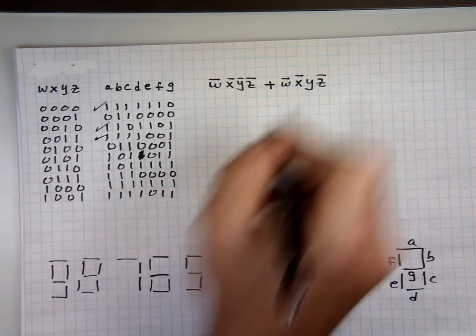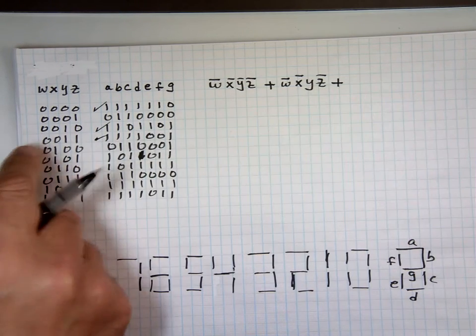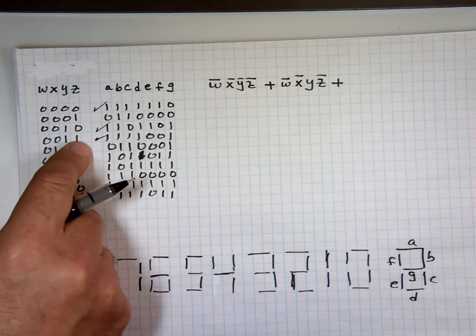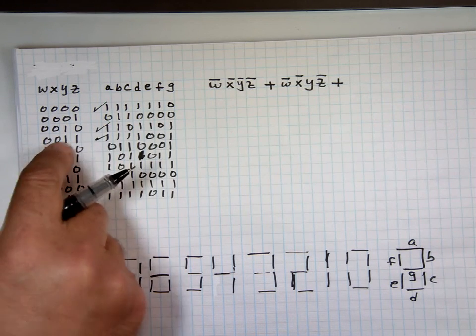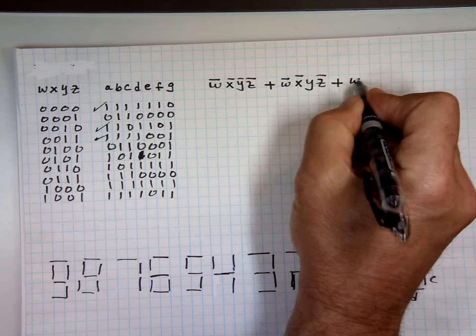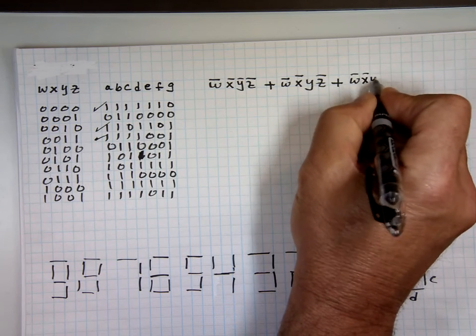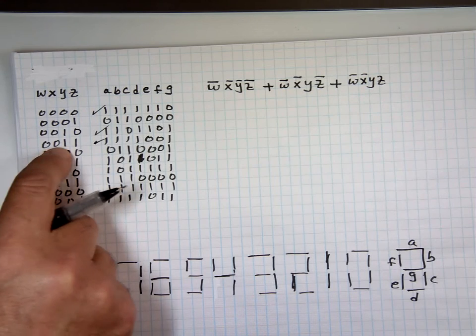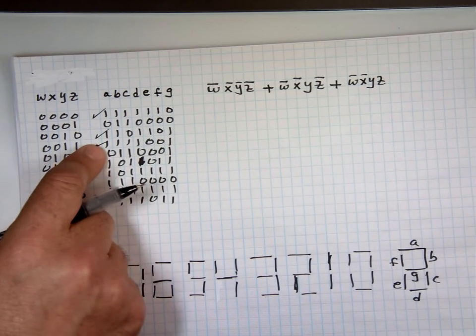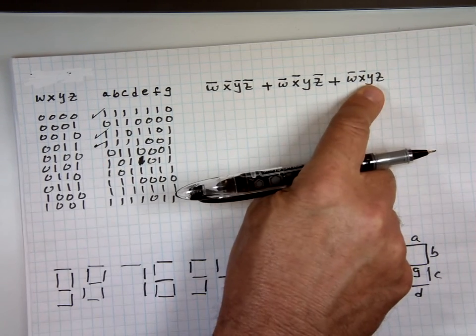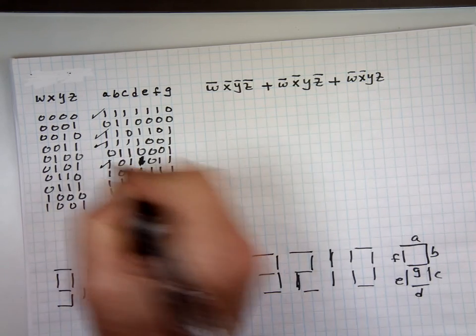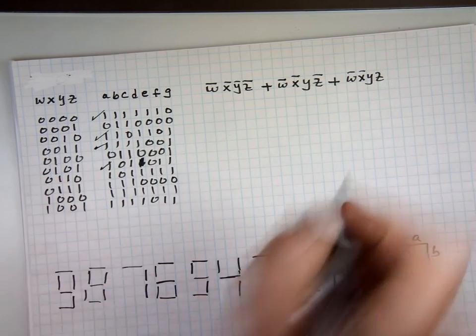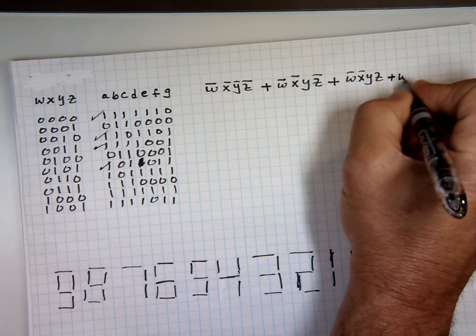These guys 0, these are 1s. So an AND gate, complement W bar and X bar, and leave Y and Z alone. I don't want to complement these. That will take care of this situation when you have 0, 0, 1, 1. Will give me that 1 there. Keep going right here. 0, 1, 0, 1. W bar, X, Y bar, Z.